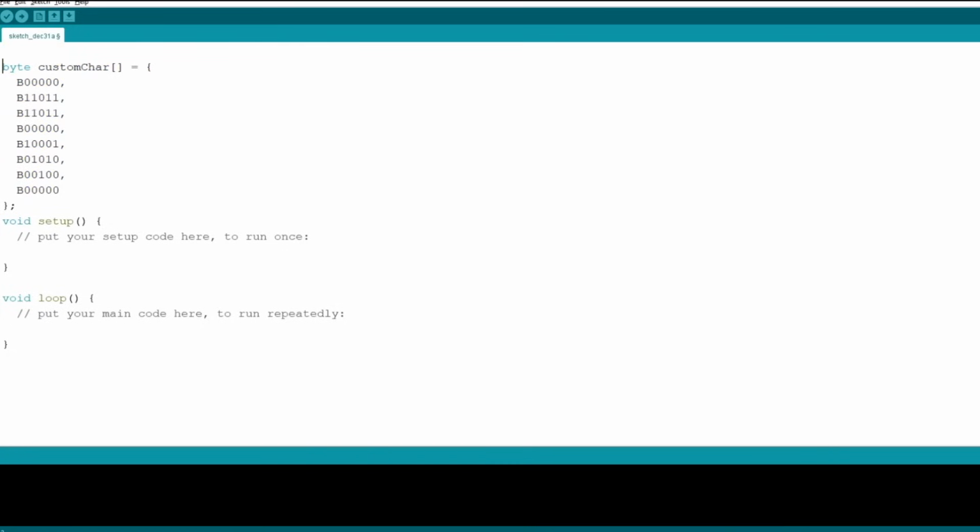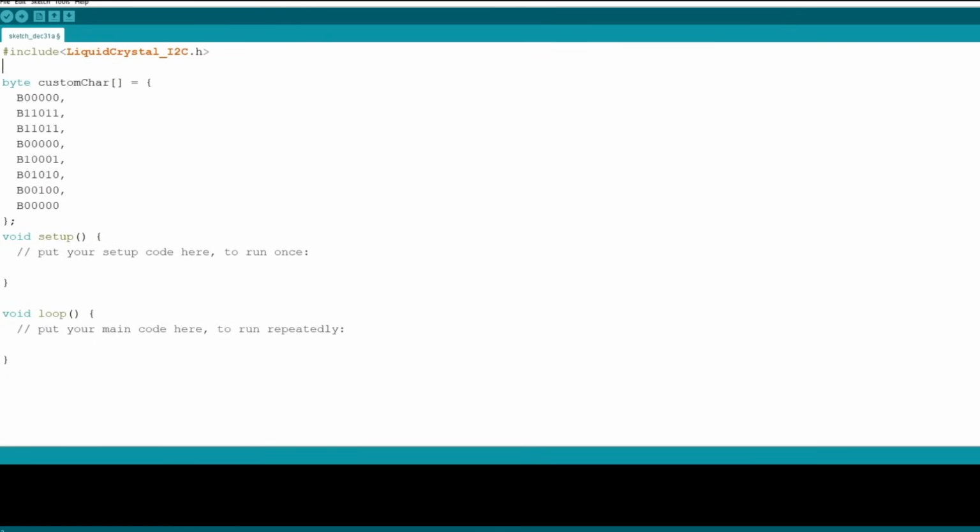And also let's include our I2C LCD screen library. So let's write include LiquidCrystal underscore I2C.h. And also let's call our LiquidCrystal class. So I will copy this and let's paste it here. And also let's define a name for our class. For example, let's set it as lcd and also open and close parentheses, and let's put a semicolon and let's move inside of our parentheses.